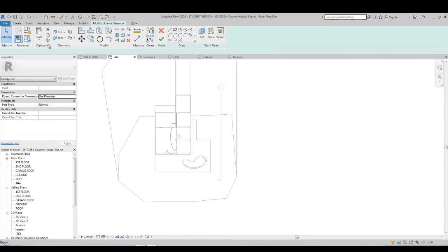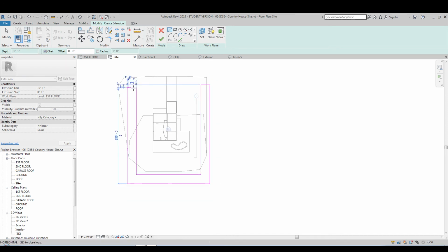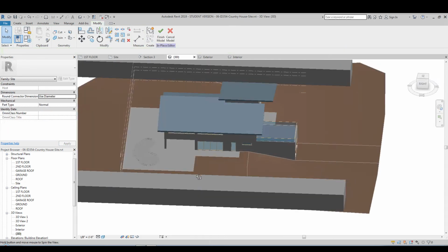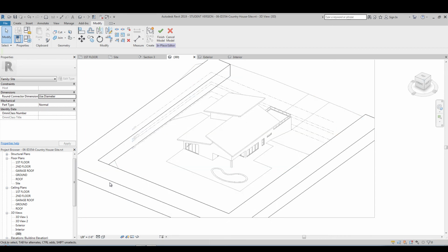And I'm going to build an extrusion, and I'm going something like this. I know that it's overlapping the side, but that's fine. And I'm doing something like this and extrude this a lot. It doesn't matter what, let's say 15 feet. The only reason I'm using this extrusion is that I can build the fence using this edge, the interior edge. And this is how I'm going to do this. Let's just make this hidden line.